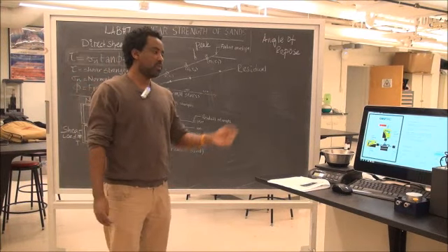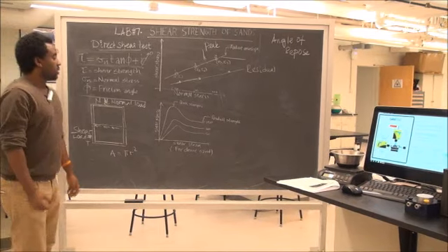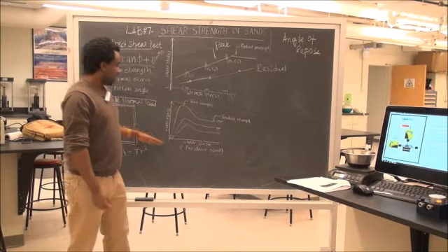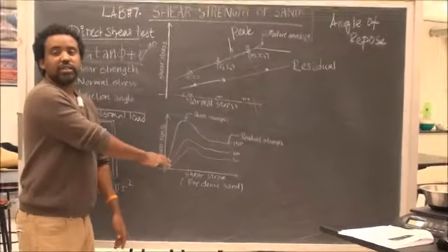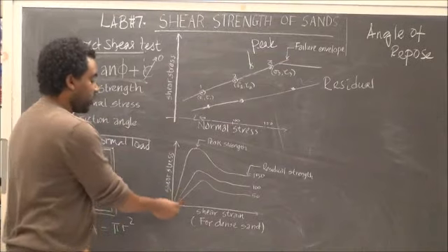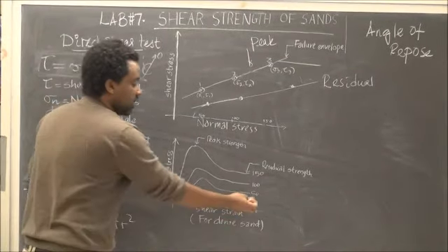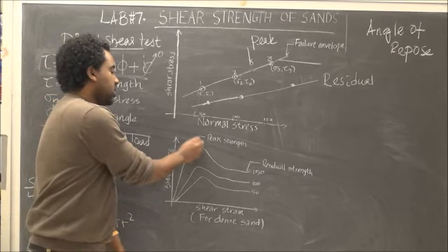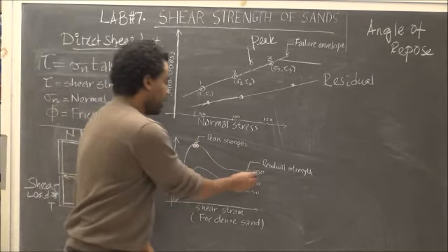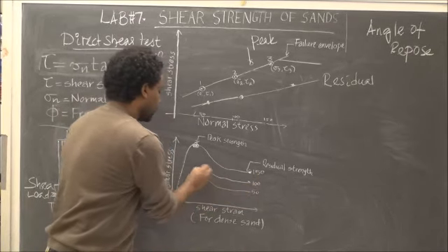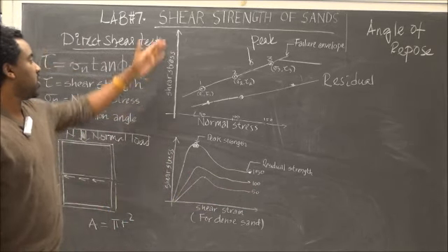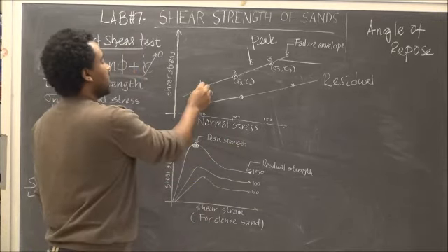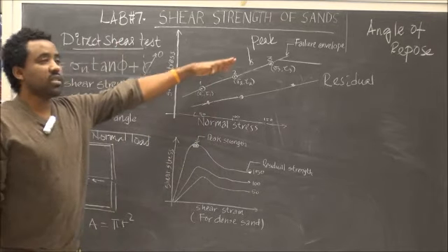Once you collect your data from the machine, the first thing you'll come up with is a plot of shear stress and shear strain, and you'll get this kind of curve, for example for 3 different tests with loads of 50, 100 and 150. From this you get the maximum or peak strength of the soil and the residual strength for each. In another plot you'll have shear strength versus normal stress, and from the 3 tests you get 3 points where you can plot the failure envelope.